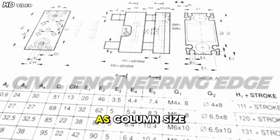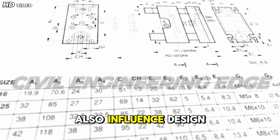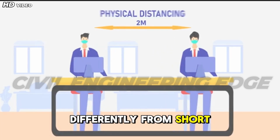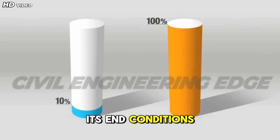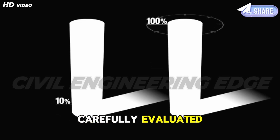Geometric factors such as column size, shape, and slenderness ratio also influence design. Slender columns behave differently from short columns and are more susceptible to buckling. The effective length of a column depends on its end conditions and framing system, which must be carefully evaluated.